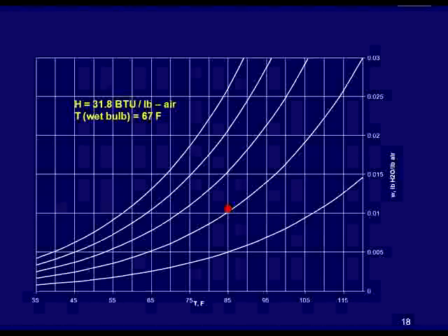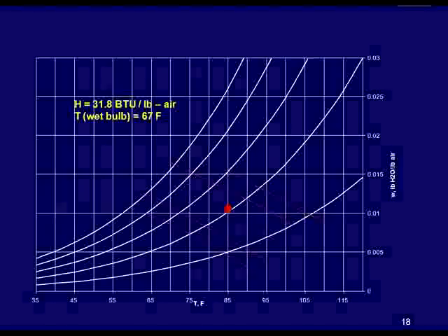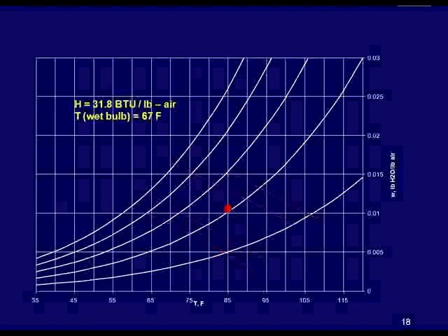Let's look at another property, and I don't have this one, the lines shown on this particular chart, but if you take out a chart from your text, you'll see these lines that go like so. And this represents the equation we put up earlier for enthalpy. Enthalpy lines run at approximately this angle. And actually, you'll see the wet bulb temperature lines run fairly parallel to those, because adiabatic saturation is very much as keeping the same enthalpy of the mixture.